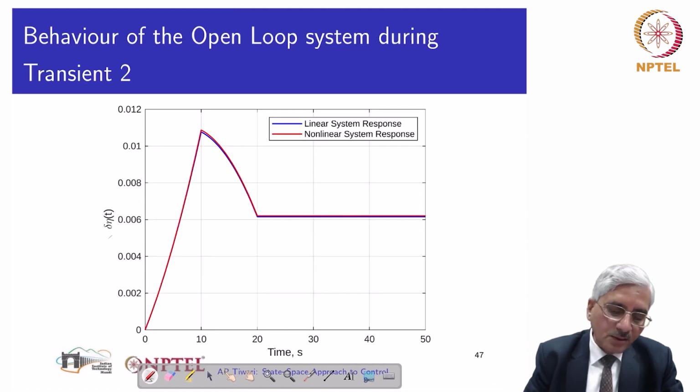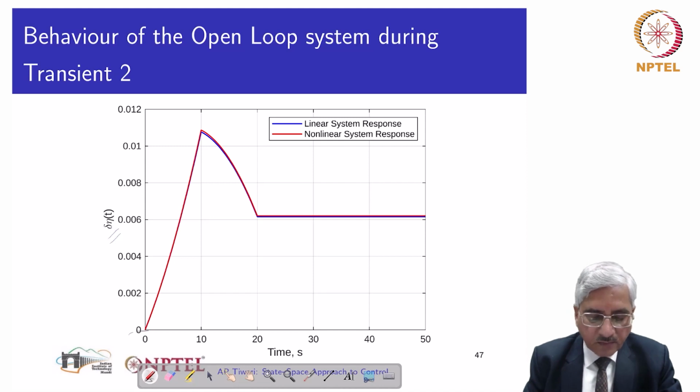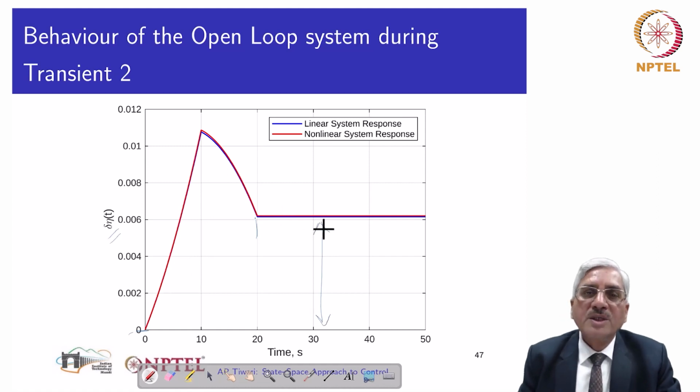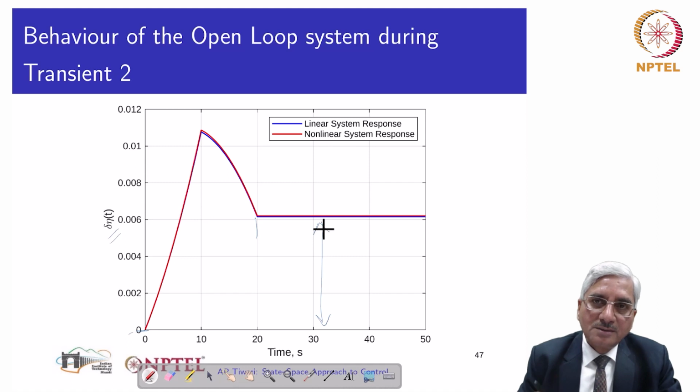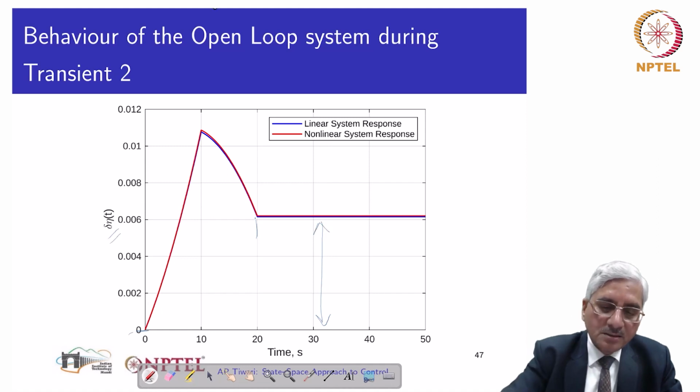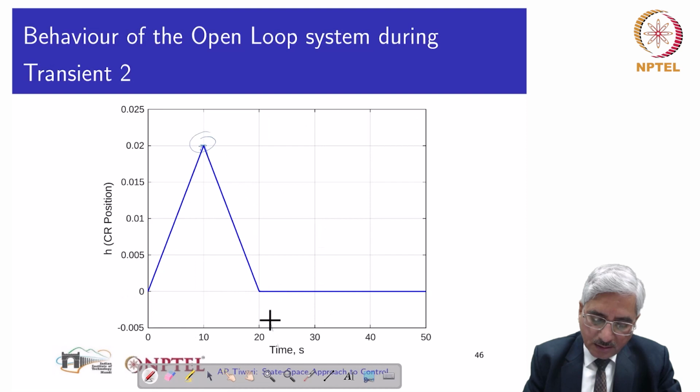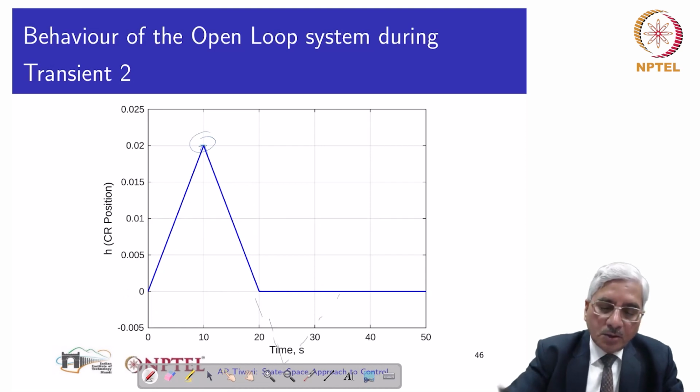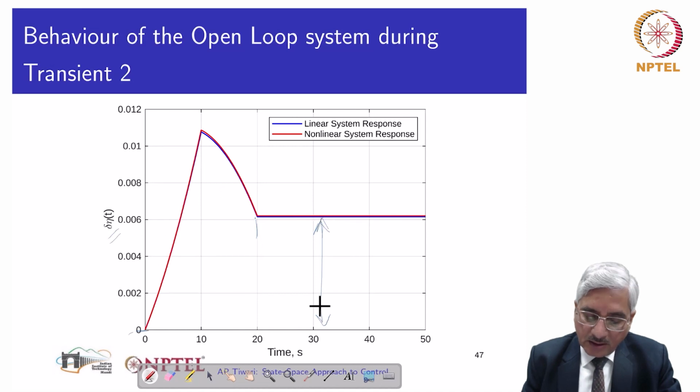This is the transient because of that disturbance voltage. And during that, this is how the neutron density has deviated from its equilibrium value. It deviated, and this is the time when the control rod came to its equilibrium position. However, neutron density doesn't reach the equilibrium position. This is a typical characteristic of a nuclear reactor. In order to nullify fully, the negative reactivity should have matched. But because the control rod was not taken on the negative side, neutron density stabilizes when the control rod reaches the equilibrium. However, it stabilizes at a different value and not at the same equilibrium.